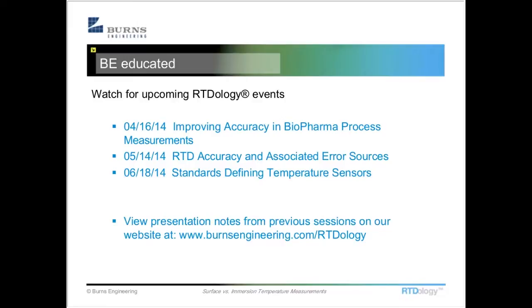If you can get the sensor into the medium that you're trying to measure, that's the best. The next best is if for some reason that doesn't work, then you put it inside a thermal well, and then if that doesn't work, you go with a surface sensor, unless, of course, what you're trying to measure is the surface temperature, in which case you go with a surface mount.